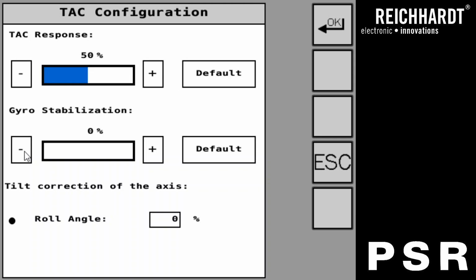With our MC controller, this is already embedded, but it's critical that our TAC MC or our MC controller mounting orientation is correct per the install instructions. Again though, for a combine, leave this at 0. For sprayers, this can be used especially on front boom sprayers to stabilize the system, but be wary that if you set this value too high, there may be more emphasis on stabilizing the machine rather than guiding to follow the rows, and may make the system too lazy.